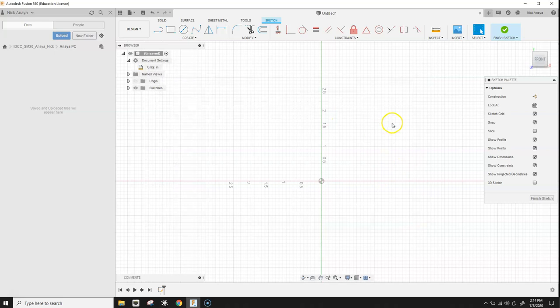All right, so now that we've started this sketch, we're going to use our line tool. So that's up here. I'm going to start by clicking on the origin. I'm going to move up in a vertical direction, so it says 90 degrees. Then I'm going to go 2 blocks. Each block has the value of 0.75, so 0.75 plus 0.75 is going to be 1.5, and then I'll hit enter.